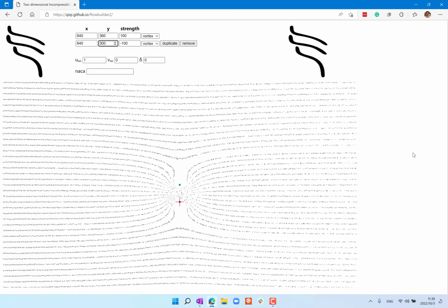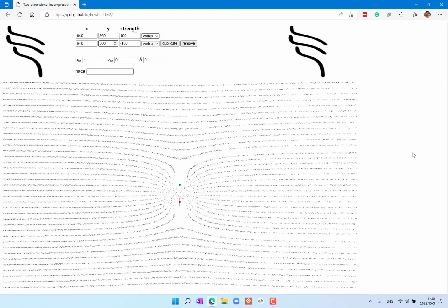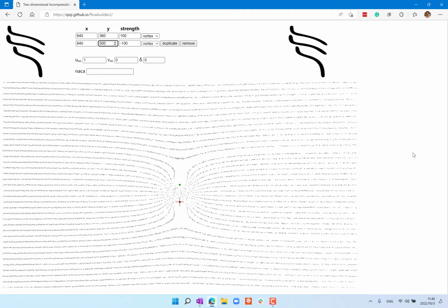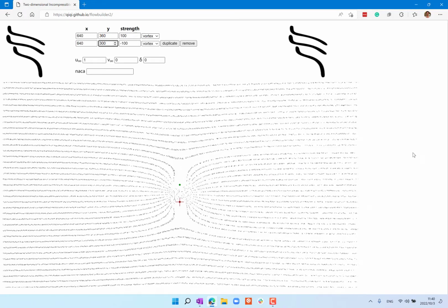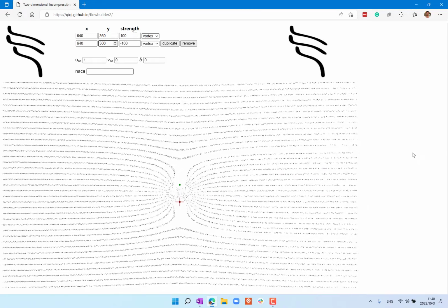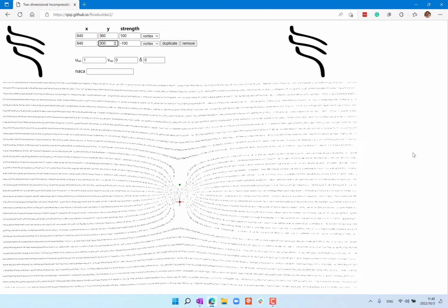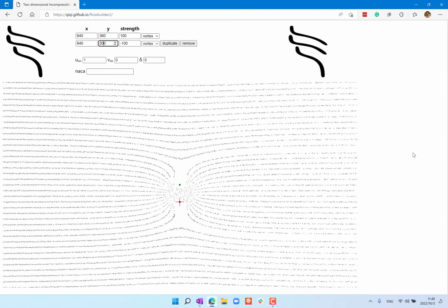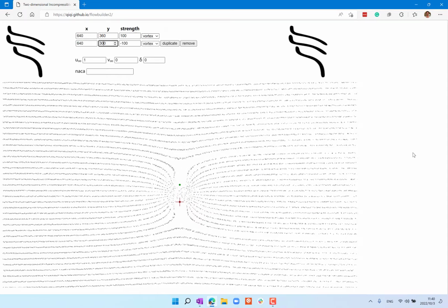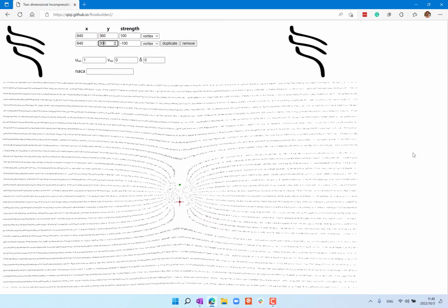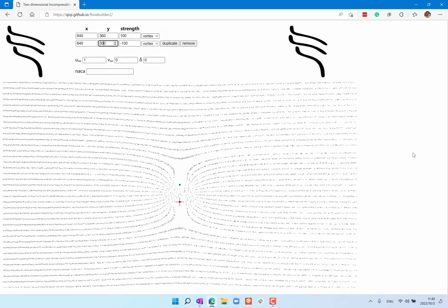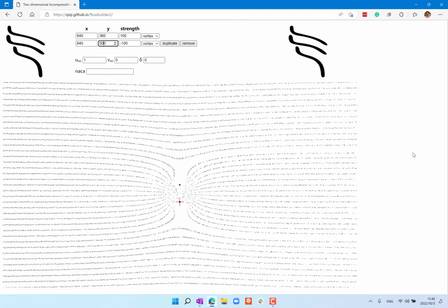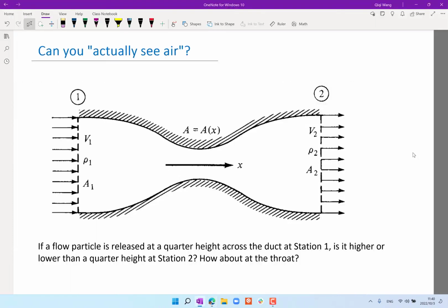So imagine the flow, right? Because we know the flow around these points is not physical, we have to look at the flow that's not including these points. So we have to put a solid boundary that protects these points. In this case, the solid boundary would be a tube that's contracting and then becoming wide again, right? That's a Venturi tube. Okay?